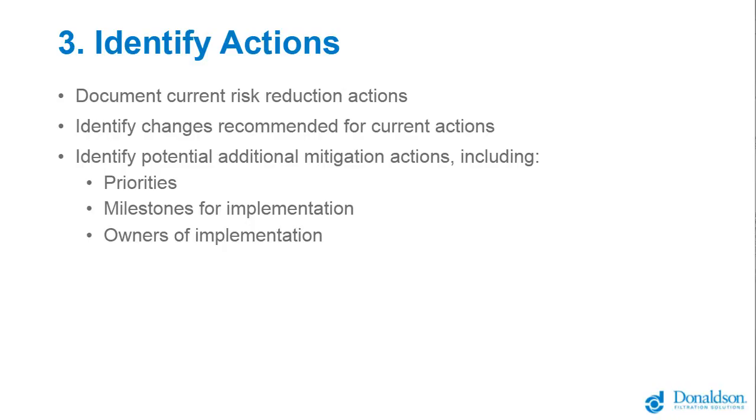When documenting what risk reduction actions could be considered to address any residual risk levels, take credit for actions which have already been deployed. For example, there may already exist an explosion vent and passive isolation valve on the inlet of the dust collector that's located outdoors and is exhausting the clean air to the atmosphere. This ensures a record of those actions in case someone decides to reverse them in the future, like deciding to return the air back into the facility.